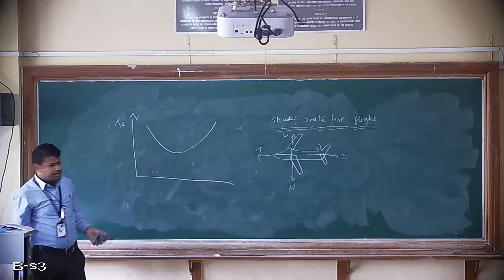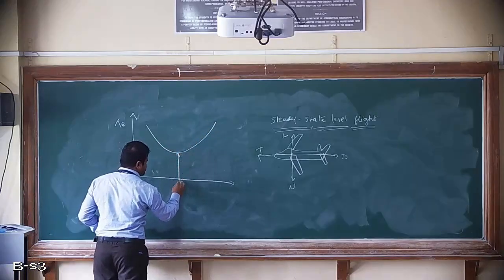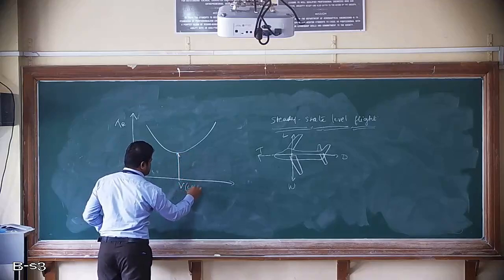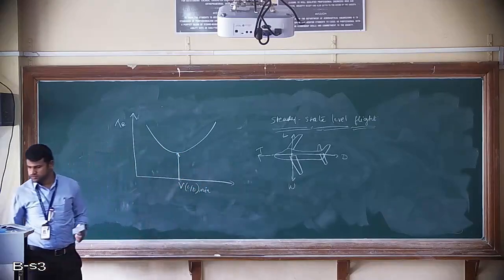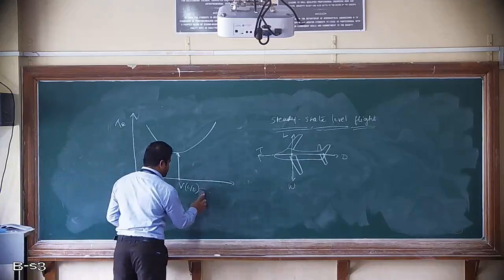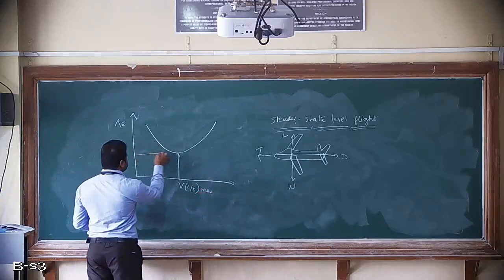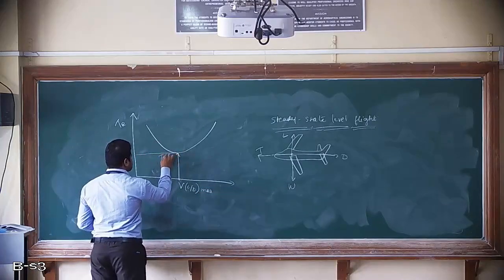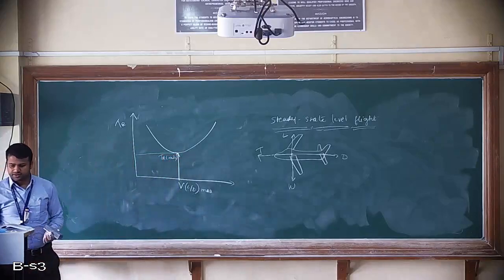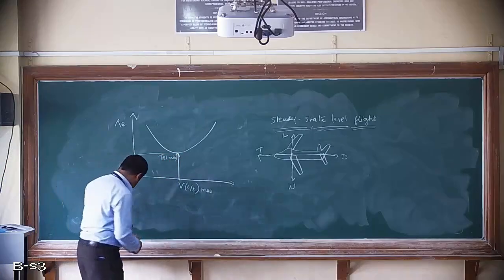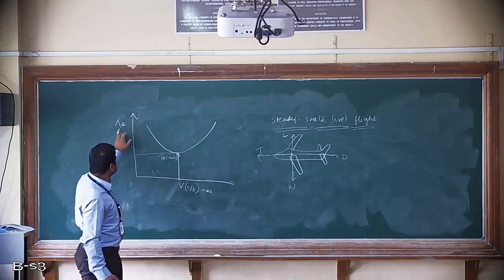And now at this point, what we wrote was minimum velocity with respect to the lift to drag ratio. Sorry, not minimum, maximum. This is maximum velocity, and this will be your minimum TR, that is thrust required minimum. So this curve is about thrust required. This is nothing but our total drag curve, but it will be in terms of thrust required.